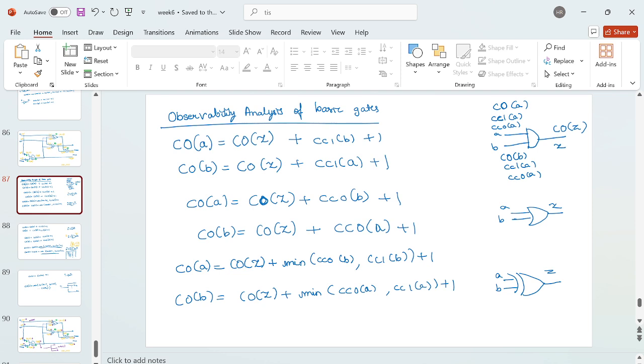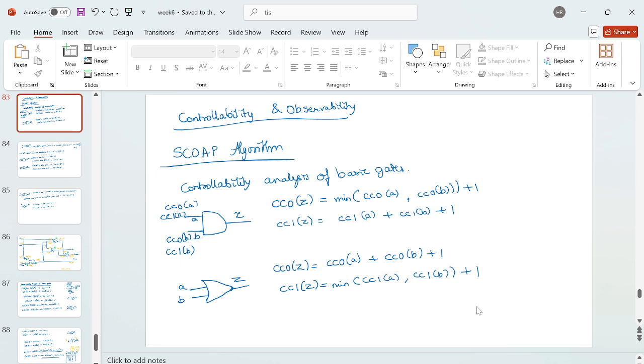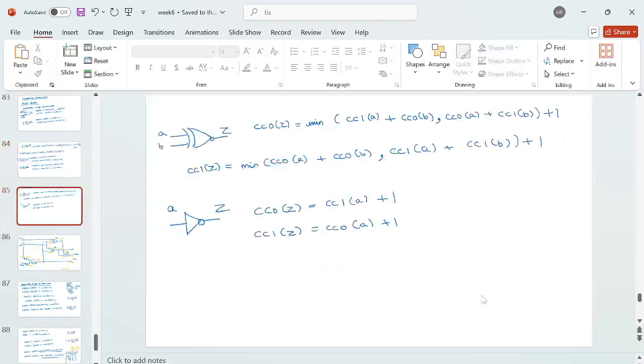In today's class, we have seen some portion of the BIST related to the response analyzer, because in the previous class we saw pattern generation. This class covered the response analyzer and compression techniques, both input-wise and output-wise, as well as the SCOAP algorithm for the controllability and observability metrics: how much effort is needed to control a node or to observe a node. Any doubts?